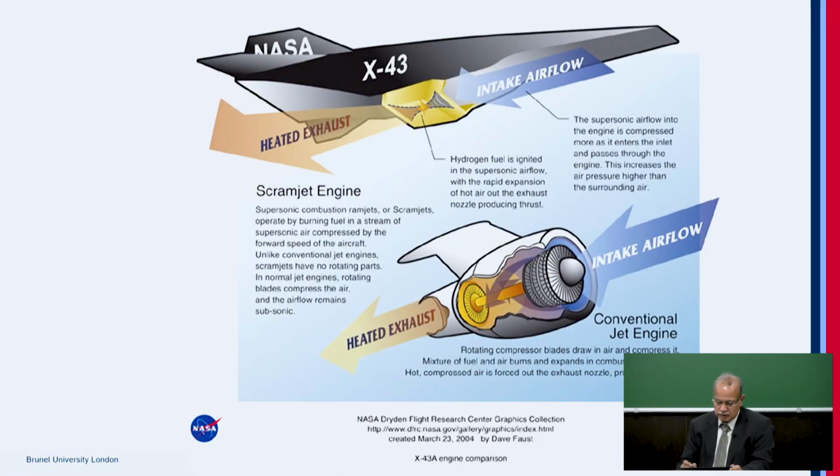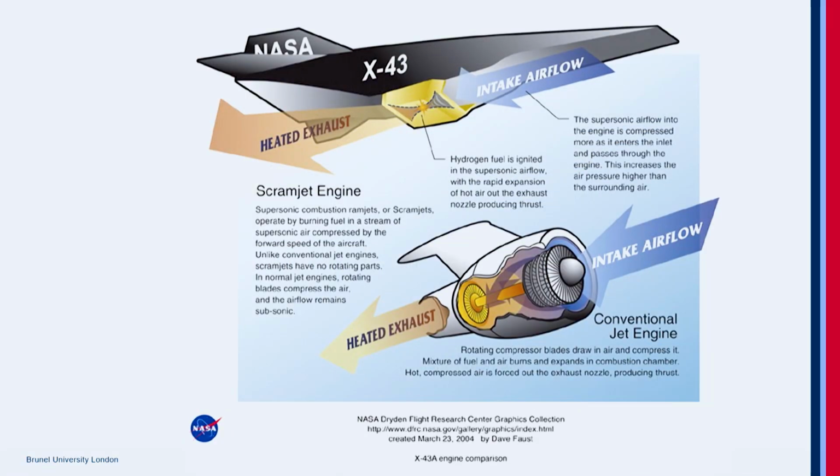Now these are the challenges, because you can't start from Mach 0. On the other hand, if you look at the conventional jet engine, you can go all the way from Mach 0 to, we're talking about, let's say if we're going for military applications, up to 2.5 with the afterburner. So this is the main advantage with these normal gas turbine based engines. But the drawback with a ramjet is that you get only high speed, but you can't take it off from the ground by itself.